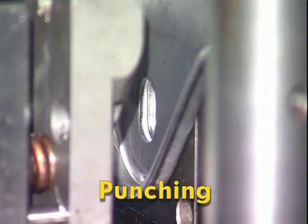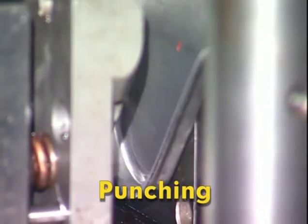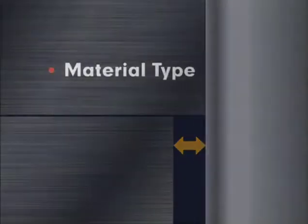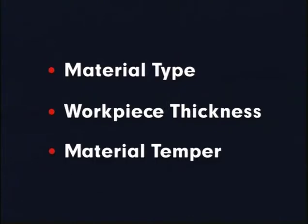Punching is the cutting of a slug from the sheet metal stock to produce a hole. Hole punching, as well as other forms of die cutting, requires specific clearance between the punch and the die. Proper clearance is a function of the type, thickness, and temper of the workpiece material.